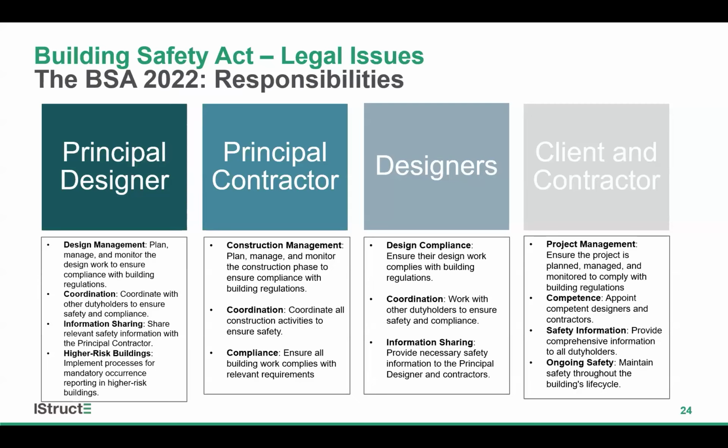So the role of the principal designer under the BSA will be taken out by somebody specifically appointed, usually the lead designer. But if no one is appointed, it can also defer to a non-specified party who fulfills the criteria for the role. So it's worth noting here that one of the potential consequences of the BSA may be claims against professionals, to include structural engineers, who perhaps unknowingly assume responsibilities as the principal designer under the Act without appreciating the obligations this entails and without having proper qualifications for compliance.